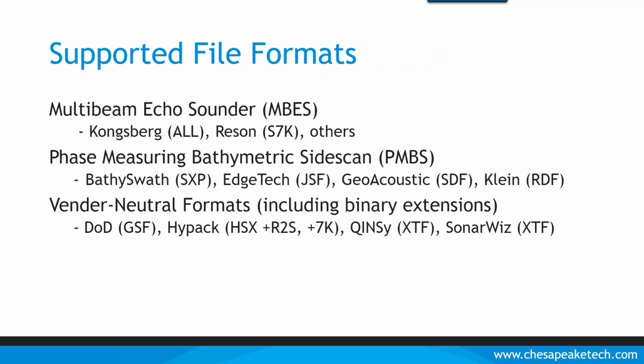So today we support multi-beam echo sounder formats from Kongsberg and Reson, primarily anything that's stored in a .all file or an S7K file, and a couple of other multi-beam specific file formats. We also support native reading of BathySwath, EdgeTech, Geoacoustics, and Klein interferometers, as well as a couple of others.